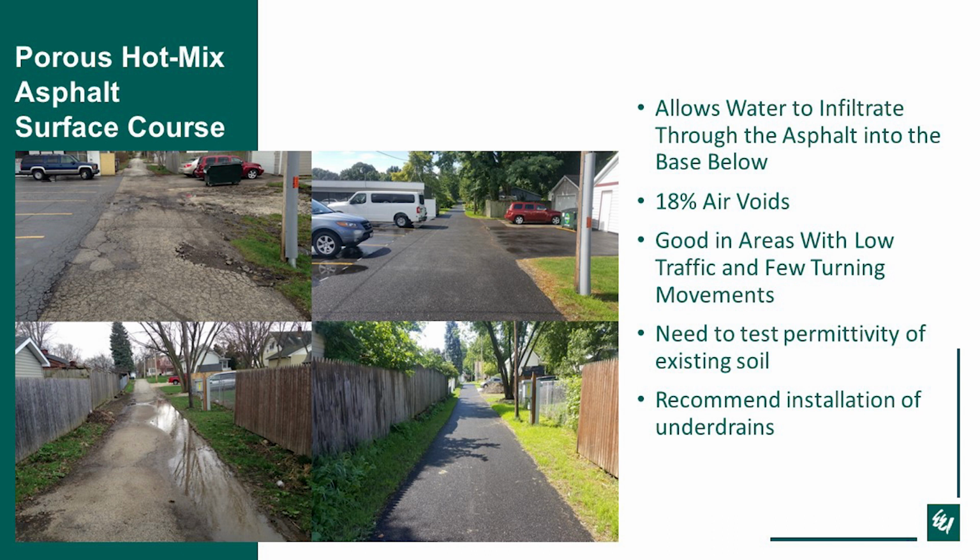Obviously, because of that, the structure of the asphalt is very porous. It's not a good candidate for areas with high turning movements and high truck traffic. In this case, very few turning movements are required, and it was just in a residential area with residential cars. So now Joe is going to talk about some of the design engineering.